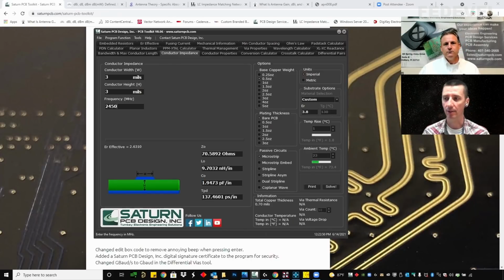I would like to mention, many people sometimes forget that when they get numbers from a PCB manufacturer, these numbers may be a little bit different, because the manufacturer has to also consider the manufacturing process itself, which is going to change some of the parameters, for example, the thickness of the electrical copper. This could be one of the reasons why the calculations in a theoretical calculator may be a little bit different from what we exactly get from the real PCB.